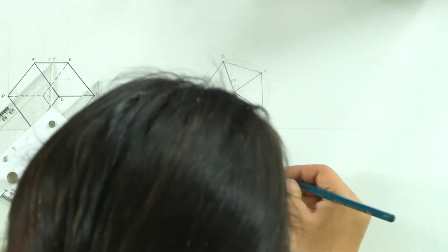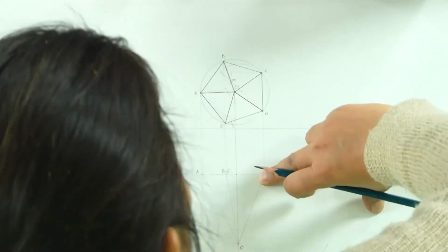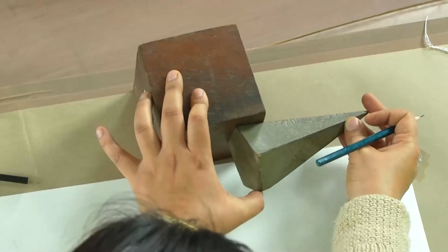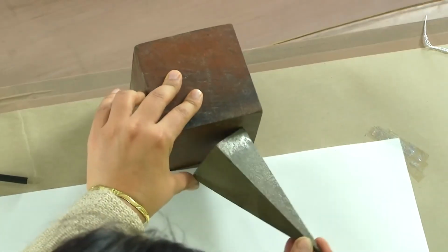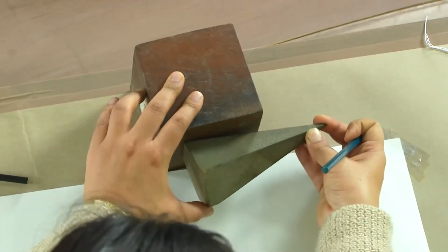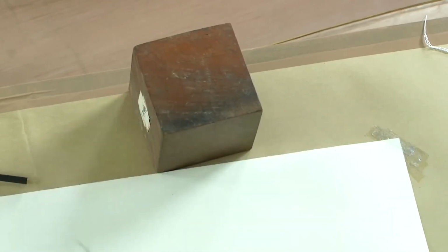So assuming that this is the point of rotation, or the side of rotation, all the points will now be taken. If you were seeing the cone like this, suppose the entire thing is now rotated in such a manner that we have this axis inclined. This axis, which is parallel to HP, which was kept like this, is now inclined to VP, right? So what do we see here?